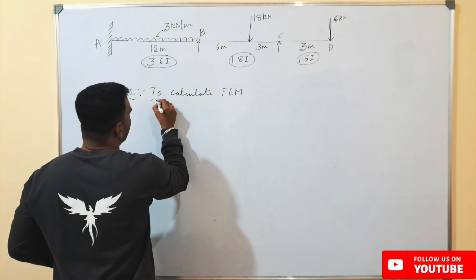So this is the fixed end moment, the total summation whatever we have got, which is plus 21 plus summation of far end rotation contribution. The far end rotation contribution here is 0 and here is also a 0. So 0 plus 0, which will be equal to, we get a value of minus 6.99 kilonewton meters. So this value will represent here, which is minus 6.99.